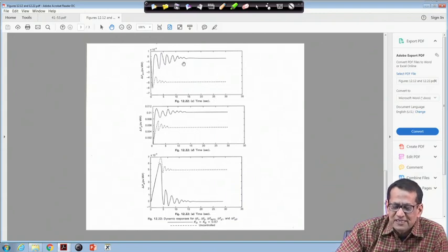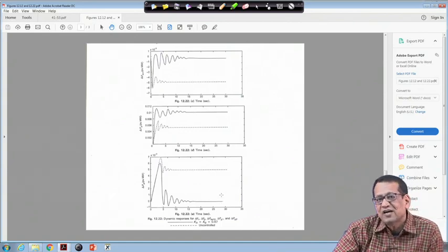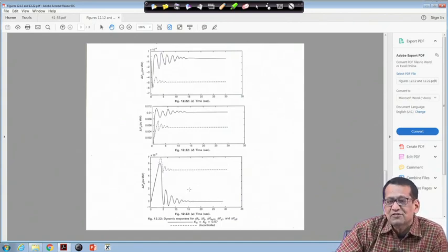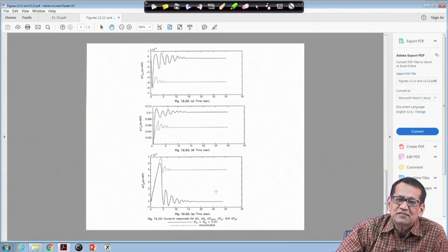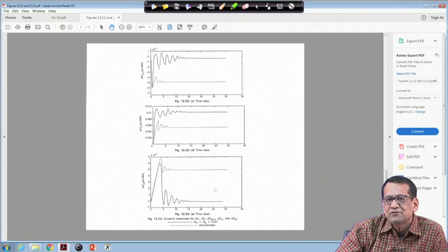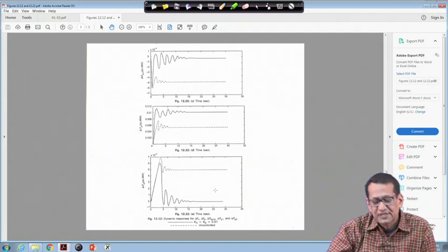So, the area 1 generator will accommodate all the load, so it is 0.01. And delta Pg2 is coming back to 0, because that load disturbance in area 1 is completely unobservable by the supplementary controller in area 2, following a load disturbance in area 1, right, when B1 is equal to beta 1 and B2 is equal to beta 2.